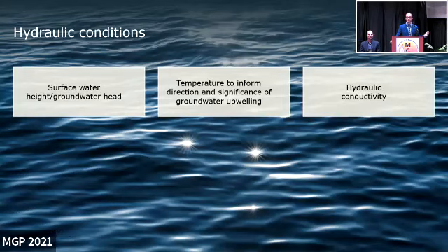I do know from experience that this is sometimes information that is hard to convince a client to collect, because in some water bodies, this is just challenging information to get if it's a navigable water body, but I strongly recommend that if you're going to go to the point of trying to demonstrate the lack of mobility of NAPL in sediment, you need as much information as possible. And so I strongly recommend getting this type of data.